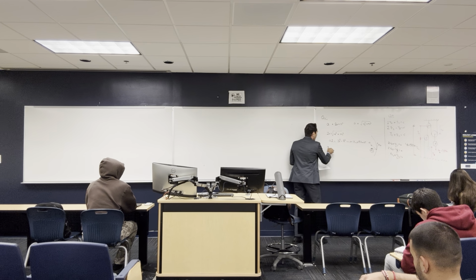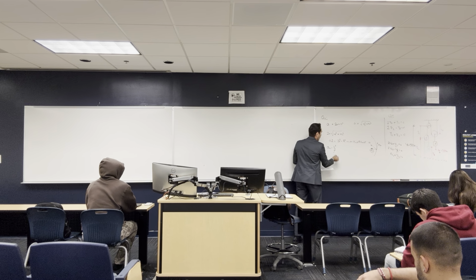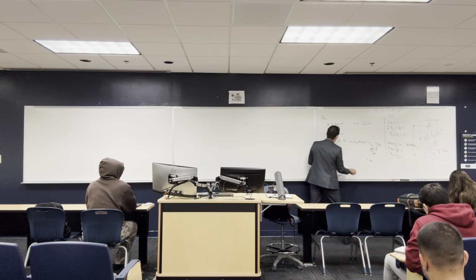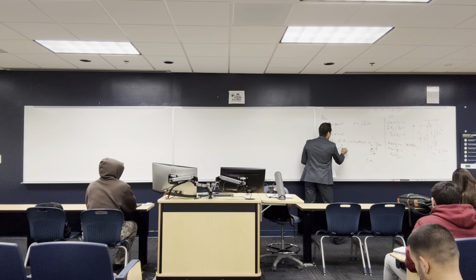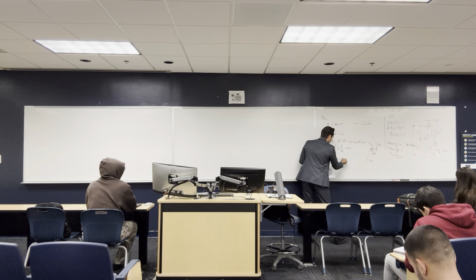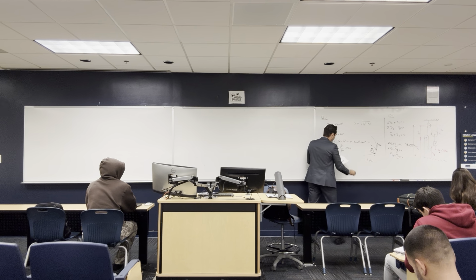And we all know that the normal acceleration is v squared over rho. I really gave you rho in the problem. That is 40 meters. So if you know that v squared over 40 is equal to 19.6, you can get the velocity, which is 28 meters per second.